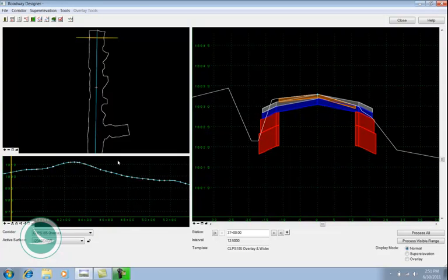Okay, so my template PGL is meeting the existing ground profile. So you can see right here at my PGL point, I'm sloping at minus 1.6%. And then I've got my orange stripping component in there, or pavement planing component in there. So the top is meeting existing ground, it's going down 1 inch and stripping that out.